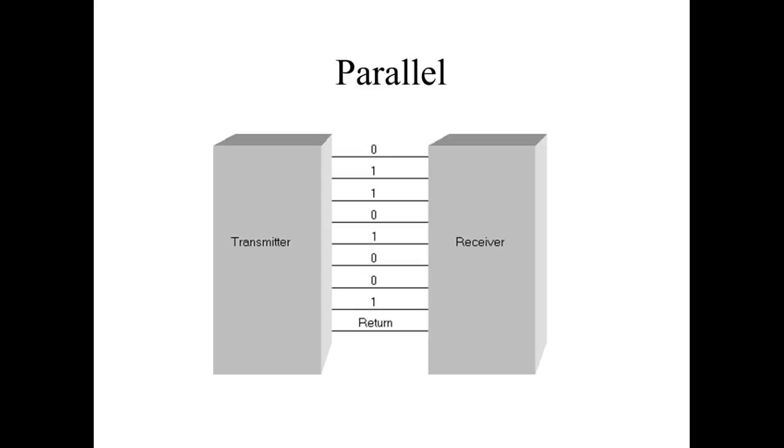So how fast would the port have to run on my keyboard? How fast can you type? Not very fast. So there's no need of using parallel for the keyboard. USB is a serial port, and we do that because of price, right? Serial ATA is a serial port. It's a hard drive port, but it's serial ATA, so it uses differential. It's a high-speed drive. We could do it faster parallel, but there's no need to, because there's no mechanical hard drive that can keep up with the parallel port.